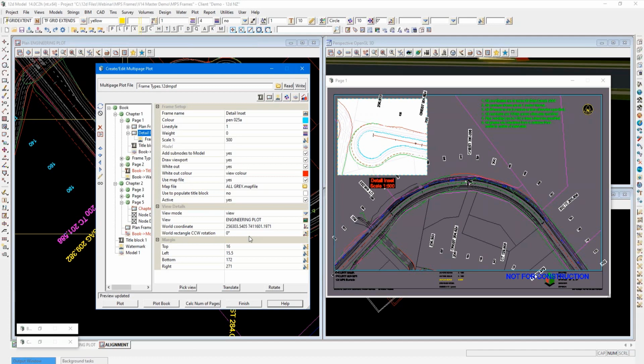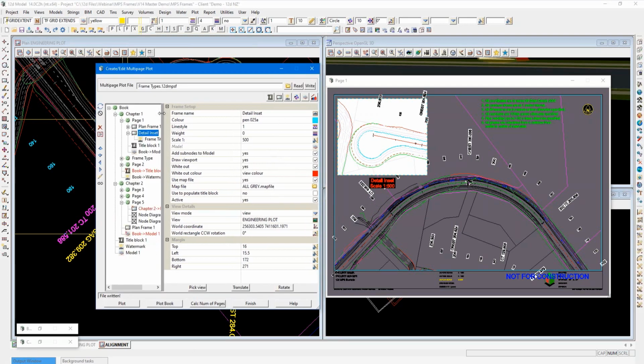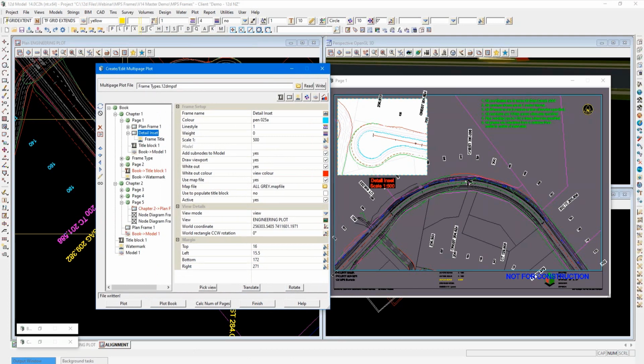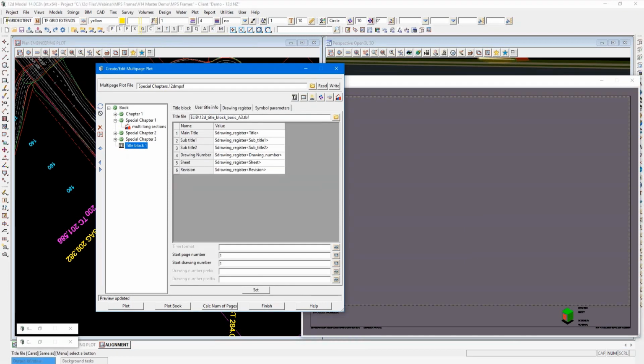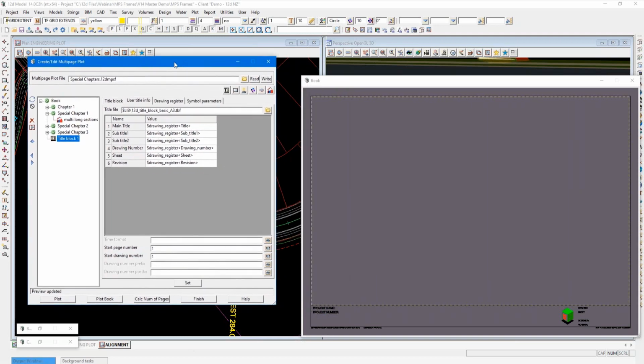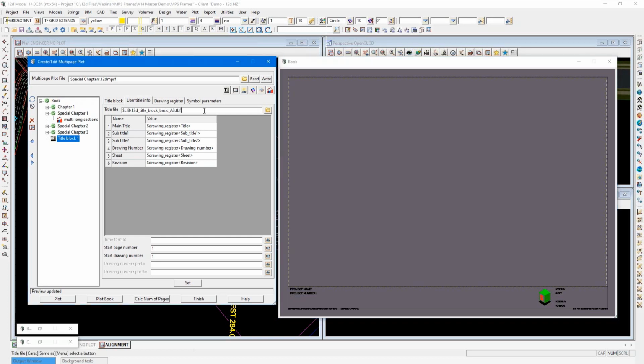Yes, we've just got a couple more I'll read out. Sure. It looks like a follow-up to the question about page numbers on special chapters. So if I'm not using a spreadsheet for page numbers, will all the page numbers automatically fix themselves still? No, they will be a user title info. So in our special chapter file where we were using the special chapters, and in the TBF file here under book level, because we were using the user title info, you would have to essentially go and change that variable type, and you could automatically number the pages 1, 2, 3, 4, 5, but if you wanted to number them 666 to 670, then absolutely use a drawing register, because you're going to have more total control over that, which is why I showed that one on a particular special chapter. Sure, okay.